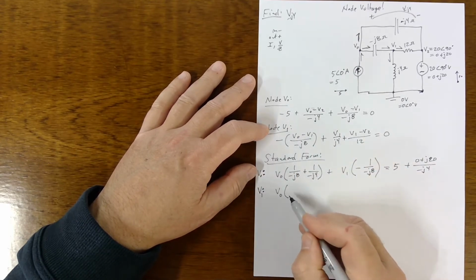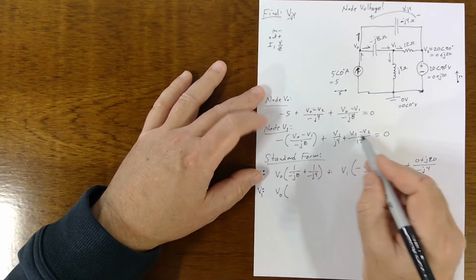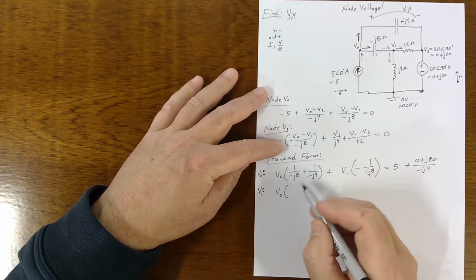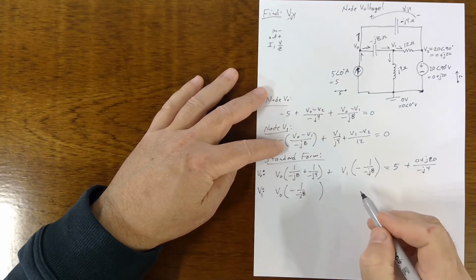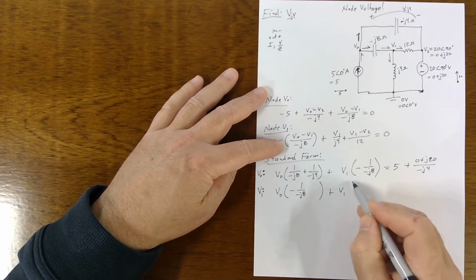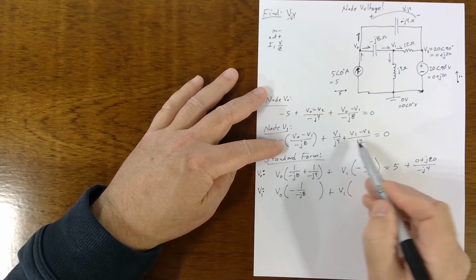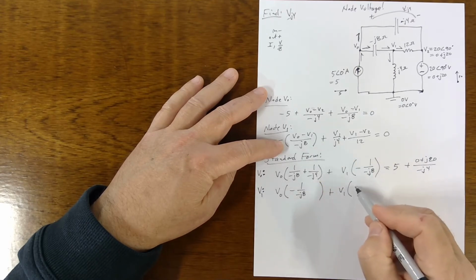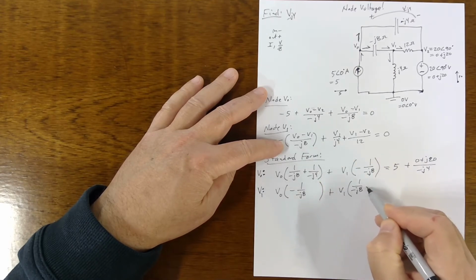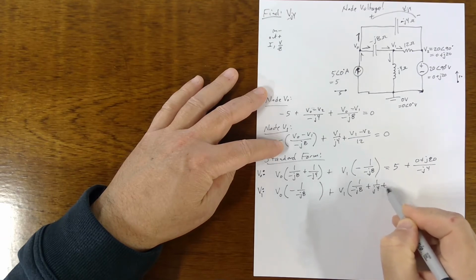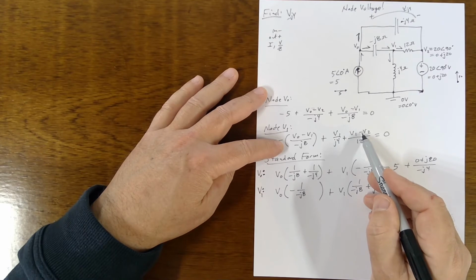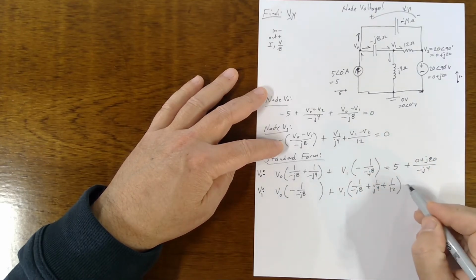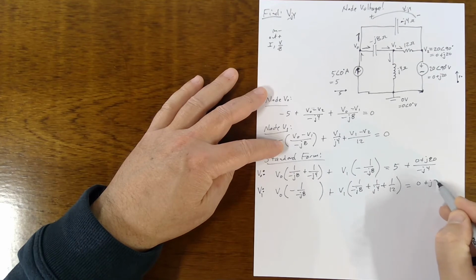Pull out the V0, factor out all of these crazy terms. You're going to get a minus 1 over minus J8. That's it for V0. And then V1 has a bunch of guys. It's got the J4, it's got the 12, it's got the minus J8. It ends up looking like this: 1 over minus J8 plus 1 over J4 plus 1/12. And then the V2 is known. Here it's negative, and it's got a 12 on the bottom. Factor it out and pull it over to the other side. It's going to be 0 plus J20 over 12.